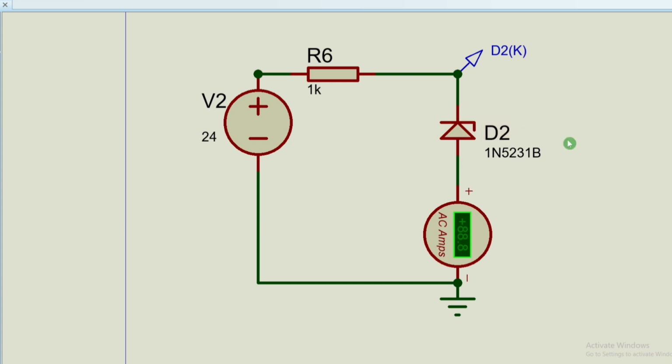So for example, I select this Zener diode which maintains 5 volt across its terminal, and 0.1 ampere can be drawn from it. We can understand that from its data sheet, which I will show later in this tutorial. So this is a 5-volt Zener diode. If I apply 12 volt over here, it will maintain 5 volt. If I apply 24, it will maintain 5 volt.